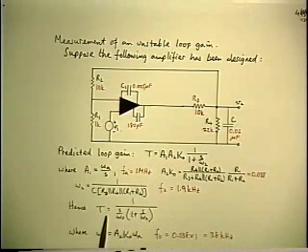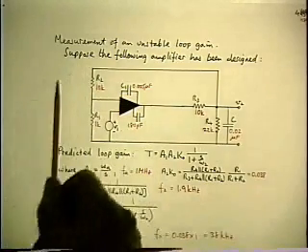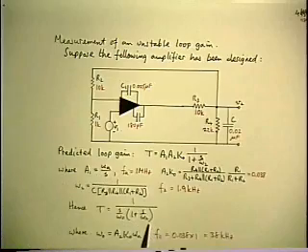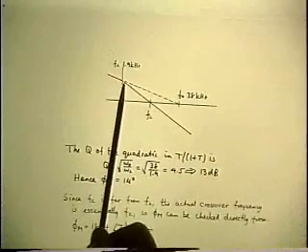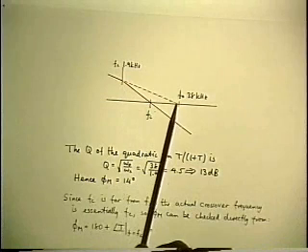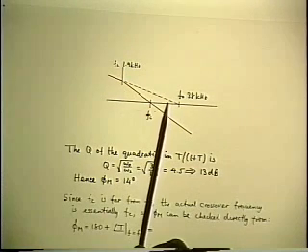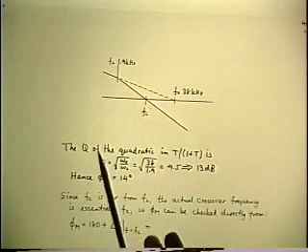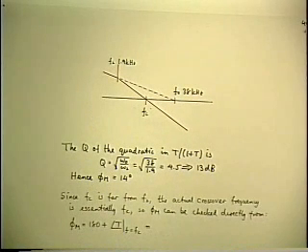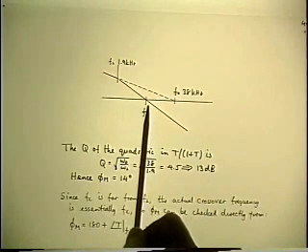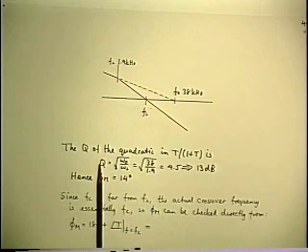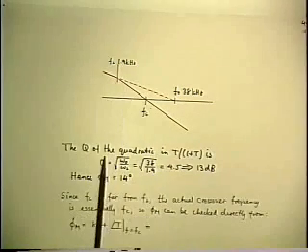And the result, once again, is a loop gain that has an initial single slope, because we still neglected the flat part at 0 frequency, and it has a second pole. And since the only difference is the numbers, the only difference in the asymptote graph is that now the second pole comes in before the extrapolated crossover, which is still part of that general case that we solved earlier on, except that the closed loop discrepancy factor now is still a quadratic, but it has a high value of Q, because the second pole is now at a much lower frequency.